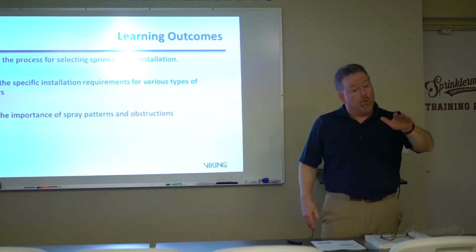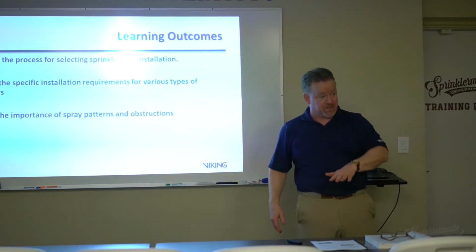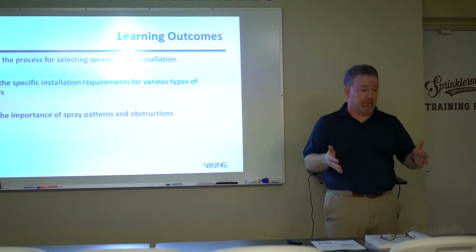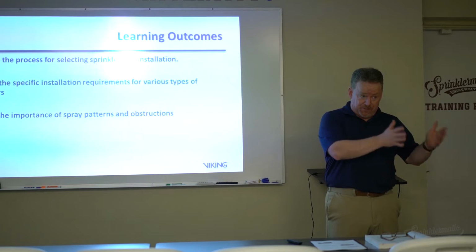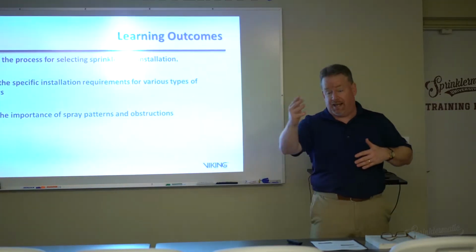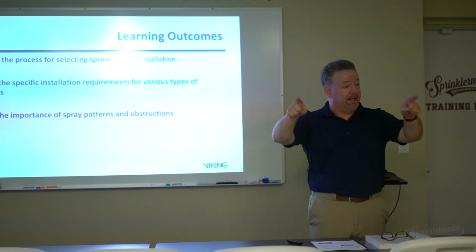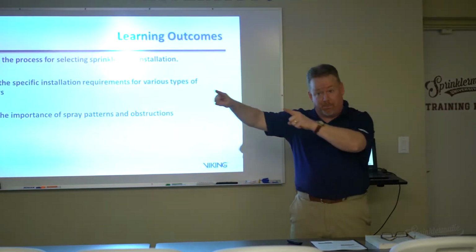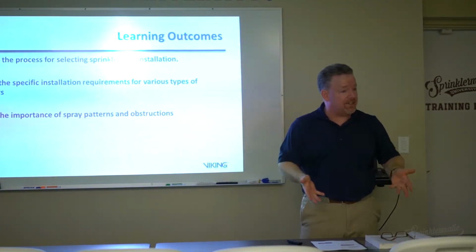However, what you do need to look at is what design criteria you used. If this particular sprinkler system was designed for delivery, remember we talked about the actual delivered density this morning, and 0.1 gallons per minute was for a light hazard occupancy.